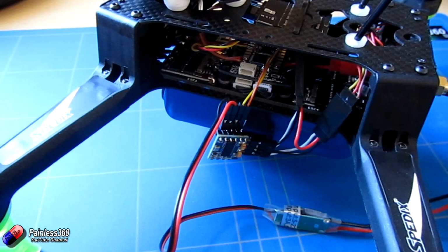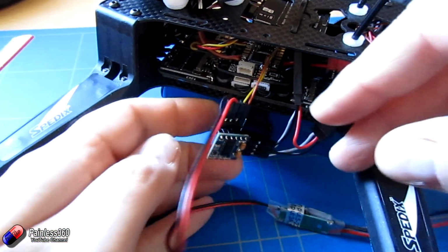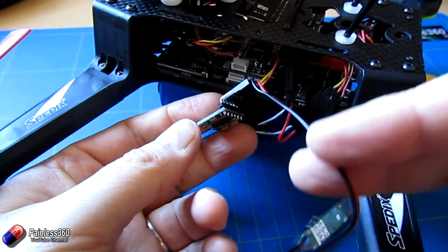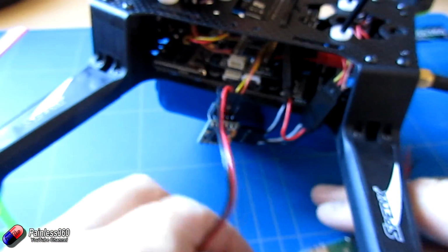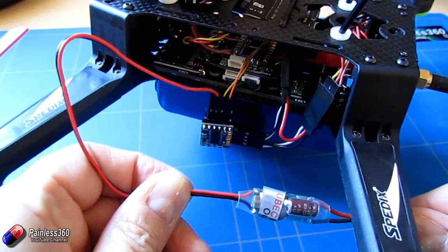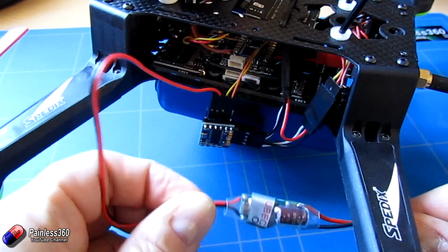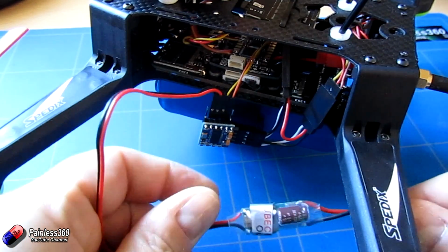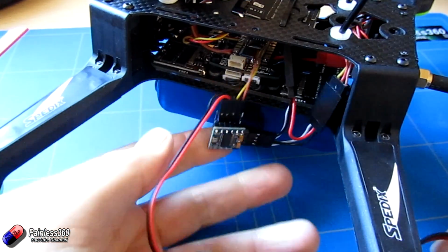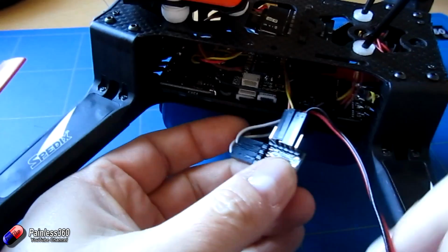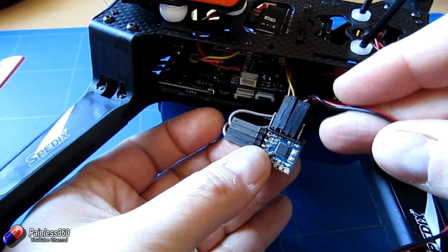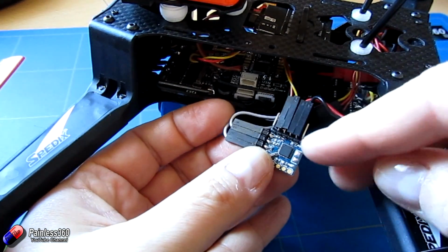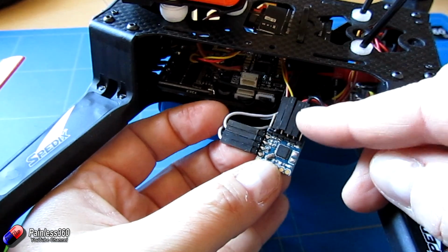Connected up to the flight controller and the craft, it looks a little bit like this. So here's the board. We have the power coming from a separate battery eliminator circuit. I've got a little one here, the smallest I could find. This one's going to plug into the flight battery, and this will provide the plus 5 volts and the ground. And the way I've got it working is I've plugged those into the plus 5 volts and ground that we plugged the FTDI adapter into.